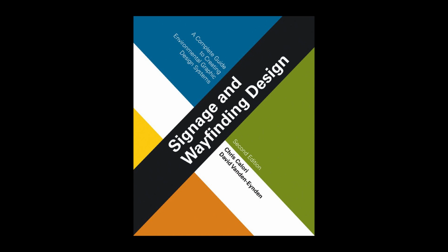If a specific material or product essential to the design of the project is only available from one manufacturer, the material/product name should be specified, along with the manufacturer's name and contact information. Such proprietary specs are sometimes frowned upon by clients, necessitating the addition of the term "or approved equal" to the proprietary spec.